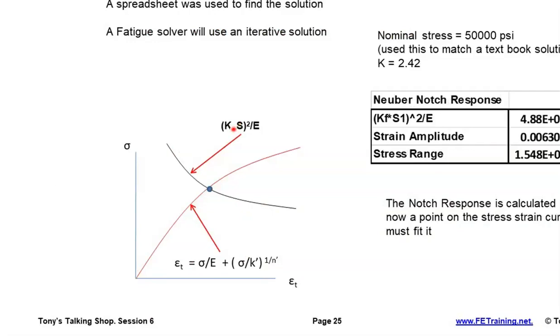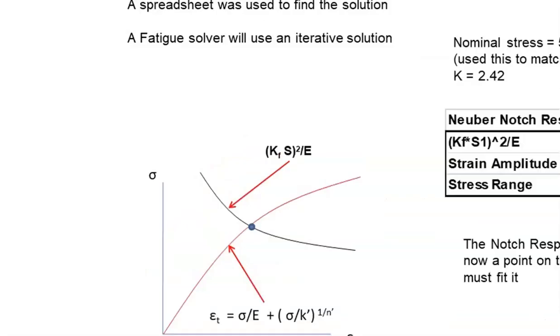That's our FEA result, elastic result. And then buried in there, we don't model the plasticity, but assuming a local presence of plasticity, that's the actual stress level and particularly strain level that we reach. And that's what we can get a handle on to include the plasticity and include these nonlinear effects. Now, getting that balance is quite tricky. In the programs I've written, I use an optimization approach to minimize the difference between that expression, at what level of true stress, true strain do those two equations balance. There are other ways of doing that.